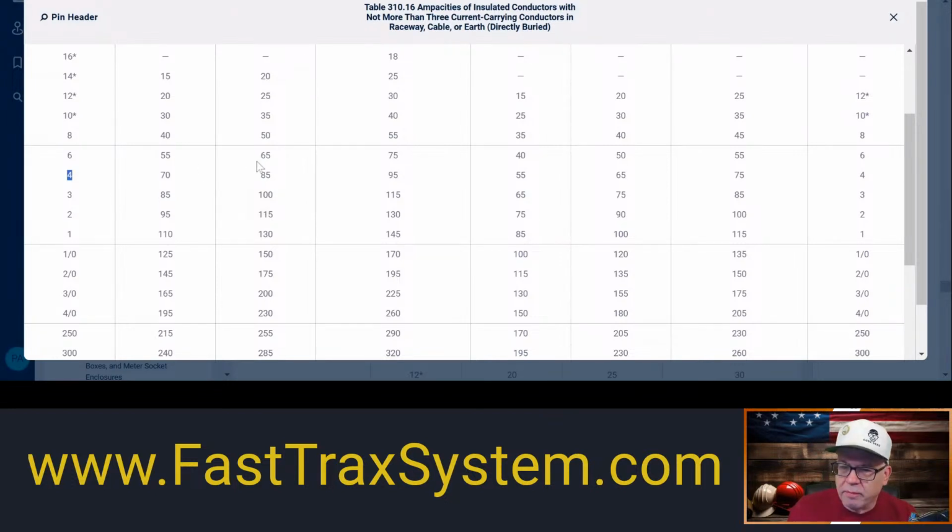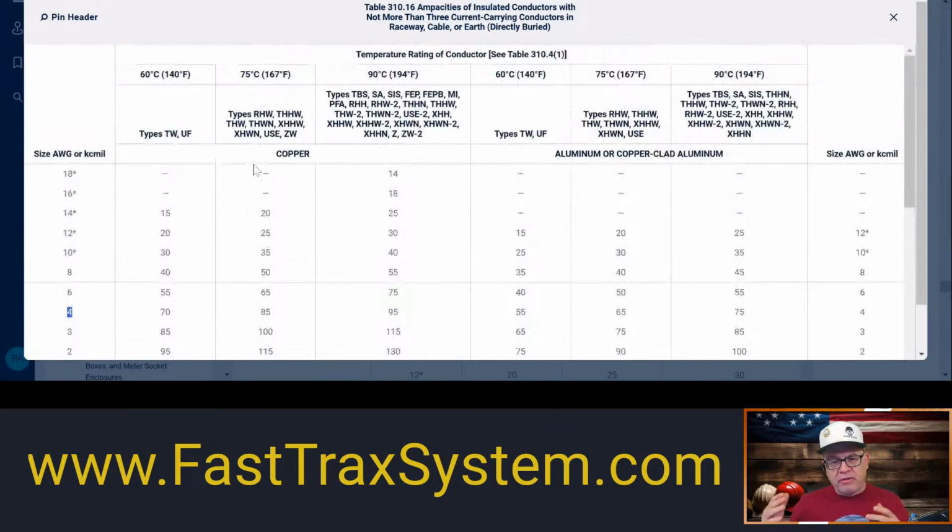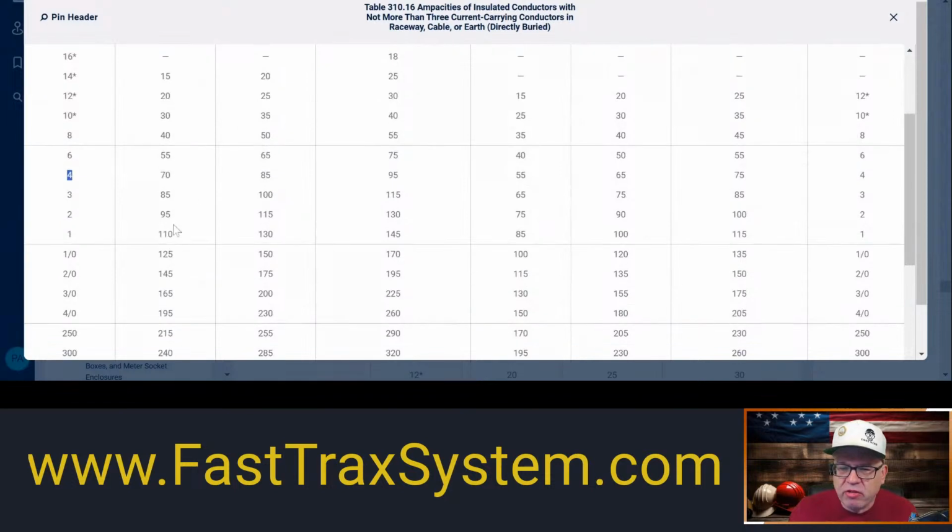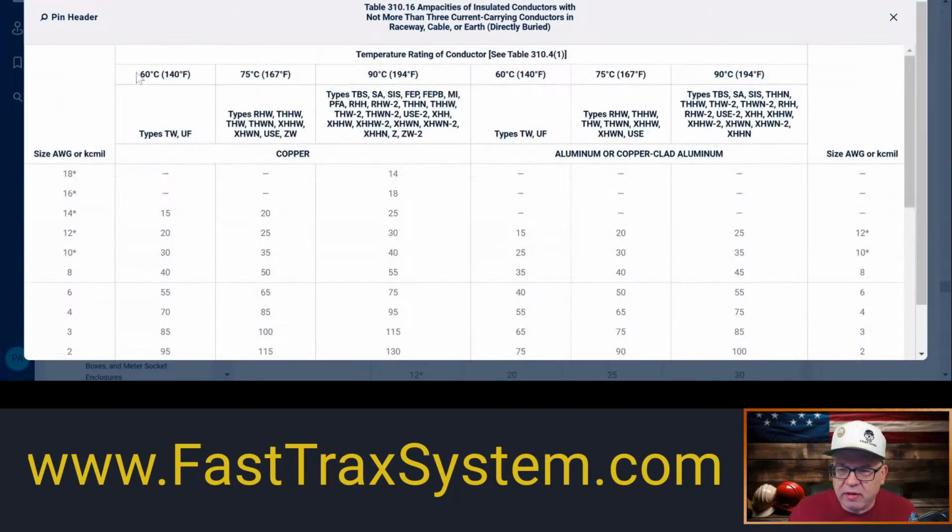Right? Now, some people will say, Paul, it's under 100 amps. It didn't really say conductor size. Why didn't you use the 70 under the 60 degree? Well, the reason for that is that typically your continuous duty motors, and it explains this, by the way, in the lesson when you're in the program. It explains why it uses the 75. But if you go look at 110.14(C), you'll see that it talks about motors. In motors, you use the 75, okay? So that is why we automatically just go to the 75.